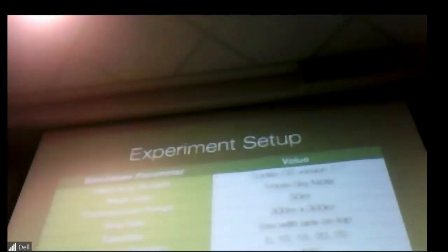I'm not completely sure right now, but if we use TCP with ambient energy harvesting sensors, and we still have that oscillating behavior, then since TCP likes to have a lot of acknowledgment packets, there's going to be a lot of loss and a lot of delay because of that behavior. I think it might even be worse.